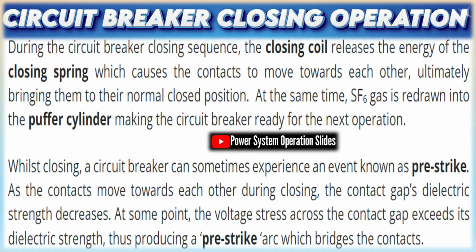Rated voltage and insulation level. The insulation of the circuit breaker externally and across the contacts should be able to withstand specified magnitudes of low frequency and transient overvoltages. Restrikes. During capacitive current breaking, the probability of restrike reignition between circuit breaker contacts should be very low.